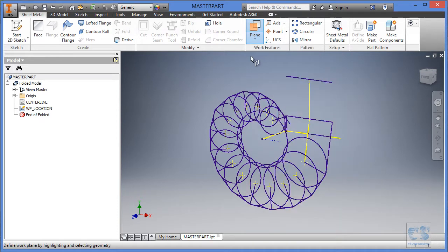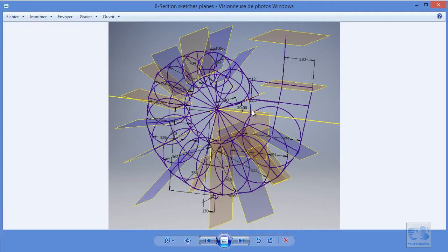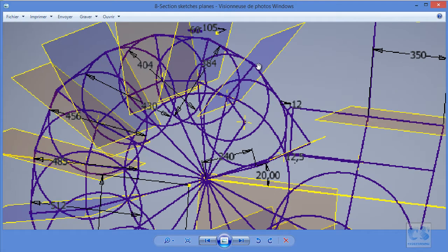So this option will allow us to define our selection as we go to get to the result we want. To create our planes, we need two inputs, and since all the planes will be perpendicular to the XY plane, we will select the XY plane first, and then we will use the work plane location lines as the second input to complete the definition of the plane.